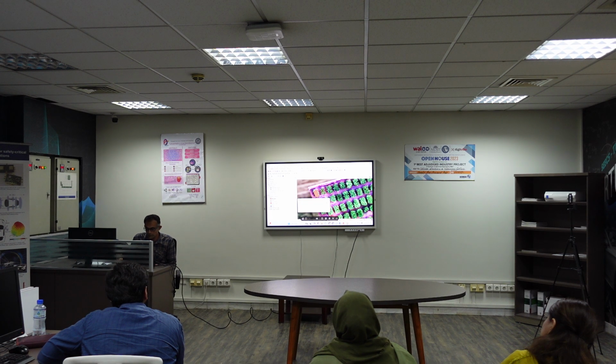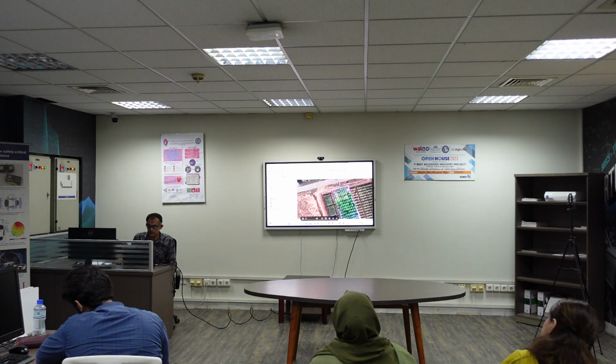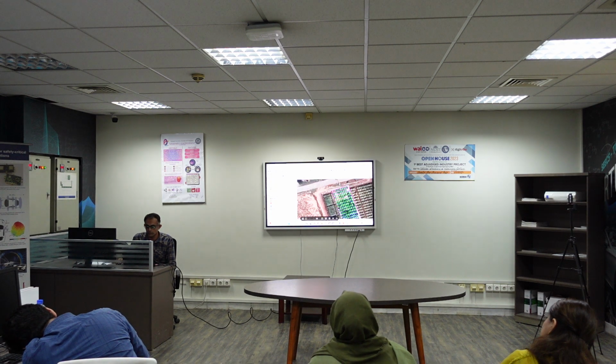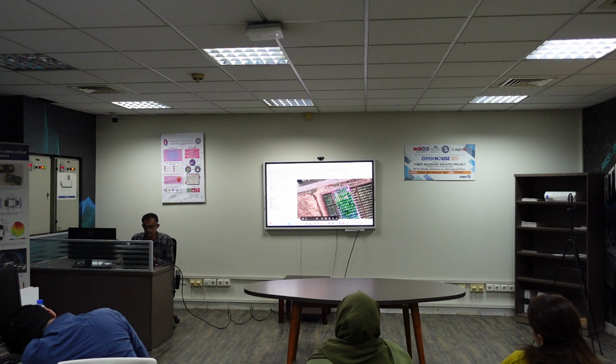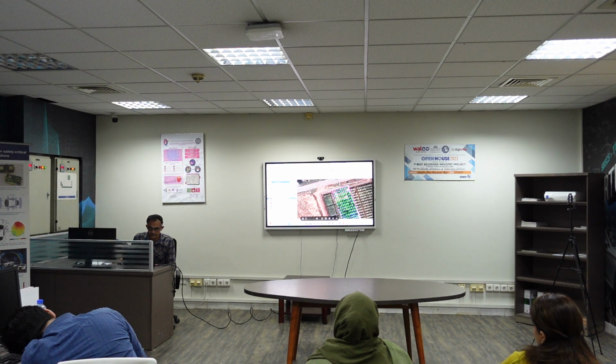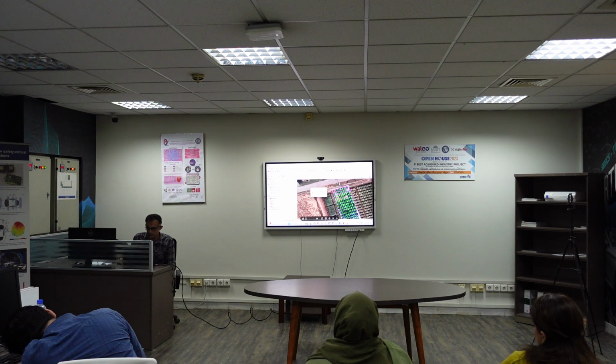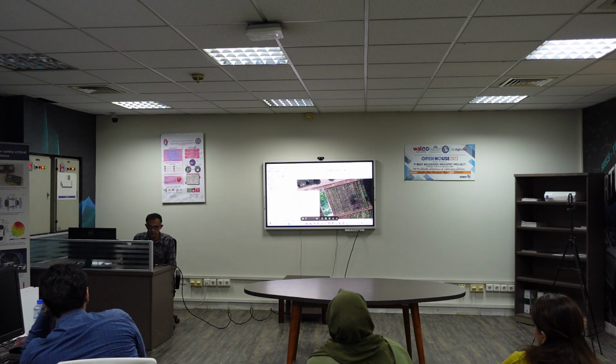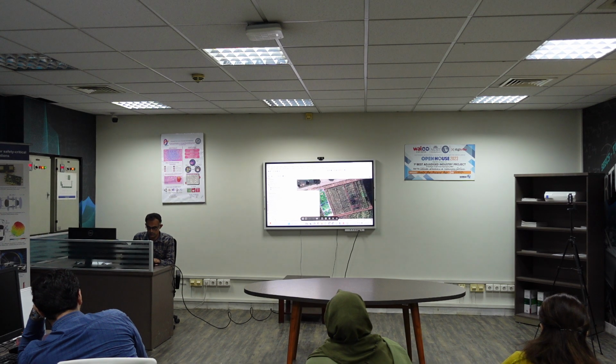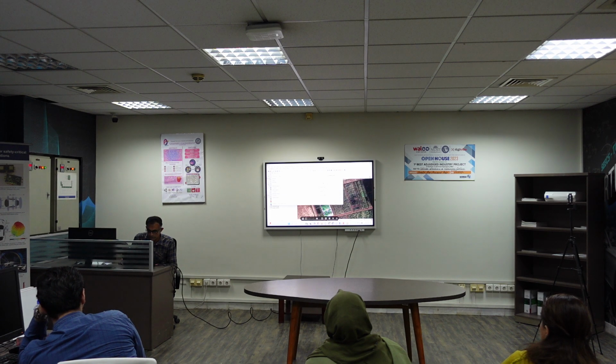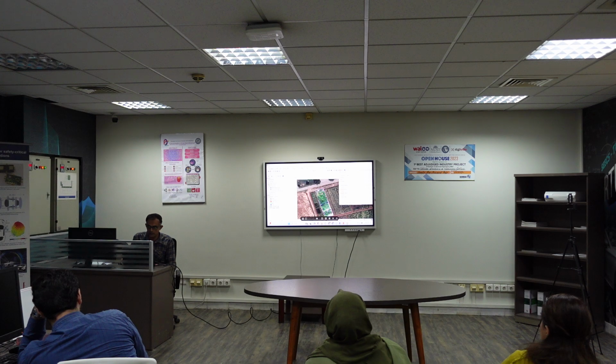Similarly, you can do this for every plot. So this is a manual way of doing this, that you have to draw a particular polygon over each particular plot, and this will be quite cumbersome for doing this for 200 plots. Another automated, or you can say less manual way, is to use a plugin called Grid. Search for grid, create grid. Now, what it will do is, it will put a grid over this area.